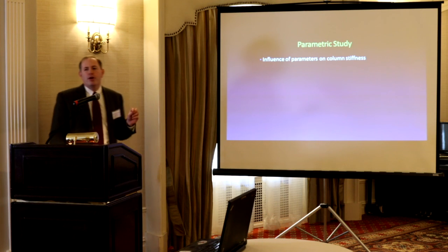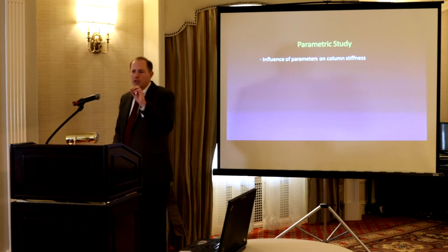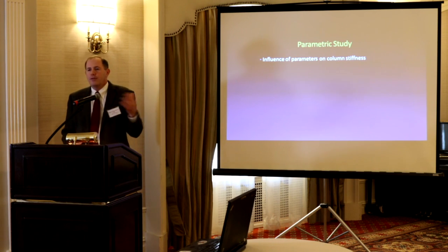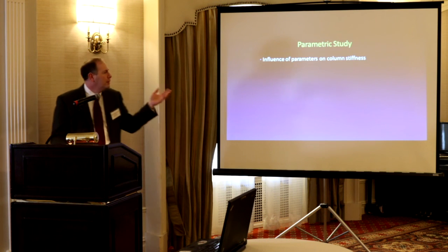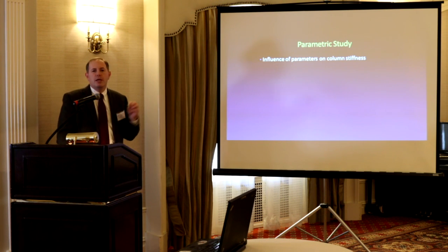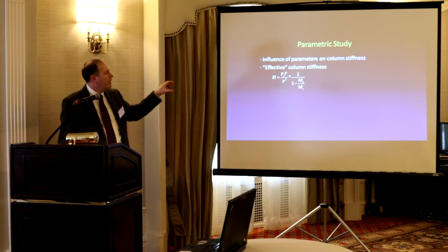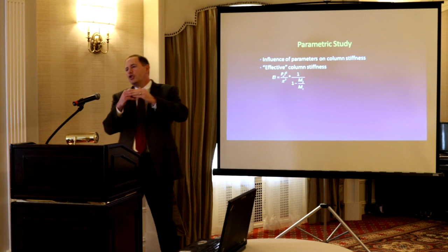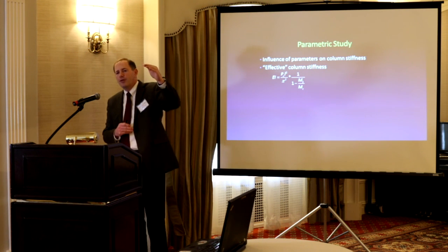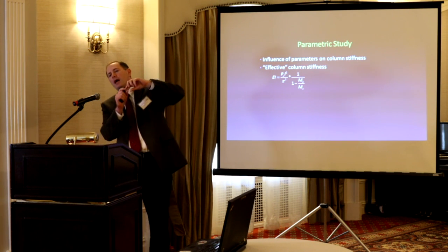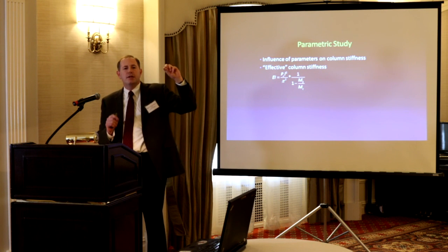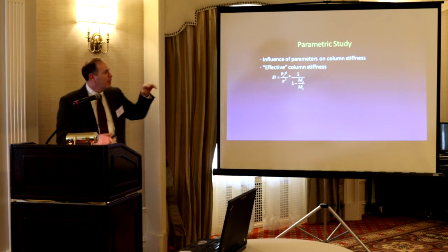Now, what we wanted to do, though, I mean, we could do that and write a software package. You could do that yourself. We don't have to write the package. You could just analyze it. But we wanted to see if we could come up with something that would be a code expression a little simpler. So we looked at the influence of all the parameters on stiffness, and we wanted to come up with an effective stiffness. Realize the variation of cracking is different everywhere throughout that column, so we need to come up with one common EI that represents the entire column, and that's the challenge.